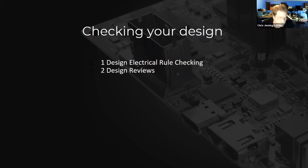But often, if you make your schematics clear enough and easy enough to follow, you'll get good questions from design review panels. And again, it's a way of reducing risk. Even though it's just at the schematic stage, there's a lot of work that goes into a PCB layout, especially a complex one. So you don't want to go through the process of laying it out and then realizing you need to rip up some logic or reroute some logic or change the device.